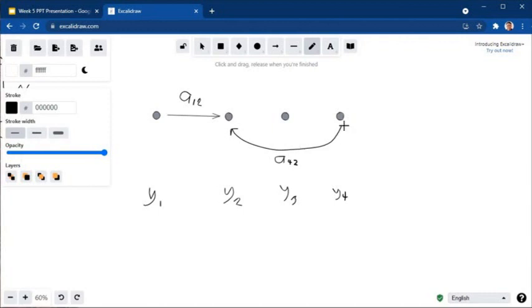So if you put it in the signal flow graph, it looks like it goes back to the previous direction like this one. If that's the case, we will label it negative. What does the negative mean? It means instead of flowing from input to output, the signal is flowing back to the input. Why is there a case like that? It is usually feedbacks. We have also discussed feedback in the previous topic and in your previous courses as well.